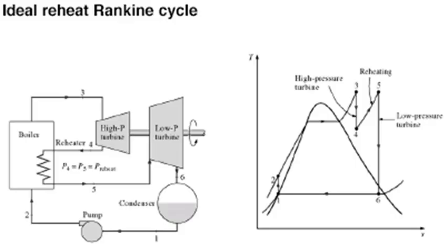Reheating is another way of improving the efficiency of the Rankine cycle with modification. Through reheating we have superheat addition at a lower pressure than the superheater, but the quantity of available heat in the process of expansion is more, thereby we get less wetness during the expansion of the steam.